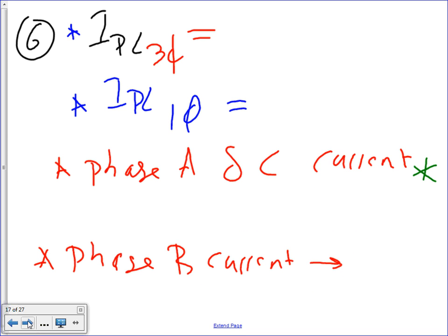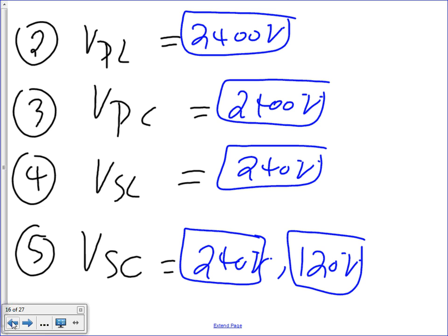Okay, primary three-phase. Now the voltage is a piece of cake, right? Voltages, did they go too fast over the voltages? The only one that I can see your point: if you're looking at it from A to B, it is 240, Chad. We just split it in the middle. But I'd like to throw in the 120 to remind you that there is a 120 voltage that you can pull out of that point, right? But you can think, again, it's 240 center tap.